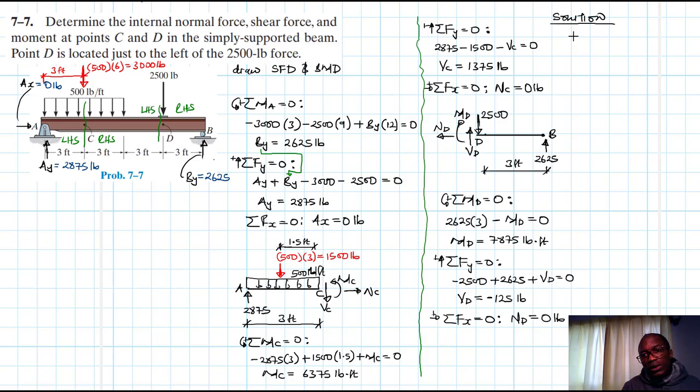Let us draw just a boundary so that we use this part of the space for working out the drawings that we are supposed to make. So we are going to use the relationship that the rate of change of moment with respect to x is equal to shear force, and therefore moment is the area under the shear load diagram.